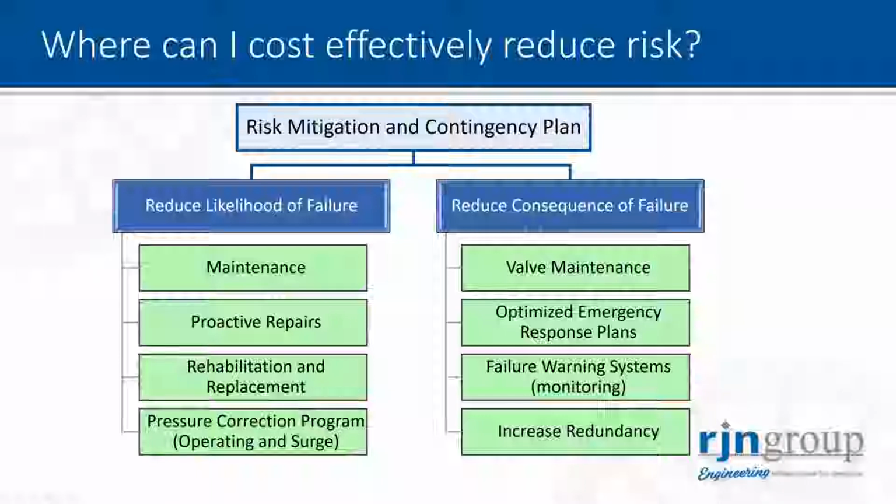Having an optimized emergency response plan, making sure that you've got the crews available or a contractor on standby, you've got extra pipe fittings, any tools needed to address a water main failure. The quicker you can get that water main back into service, the quicker you've reduced your consequence of failure.